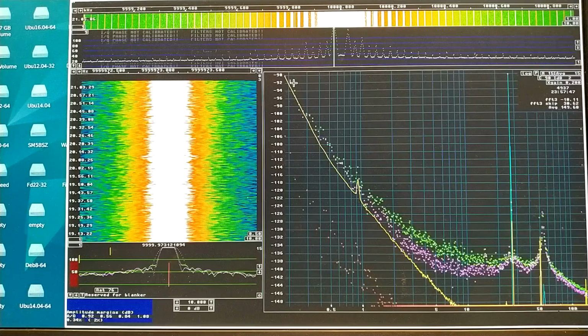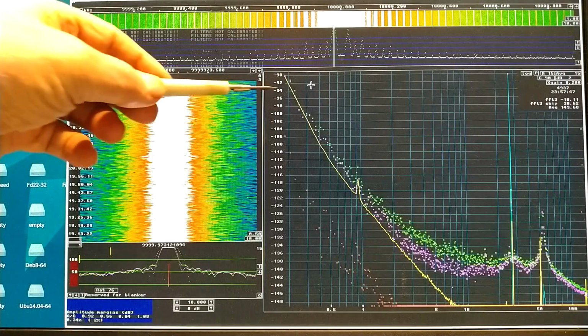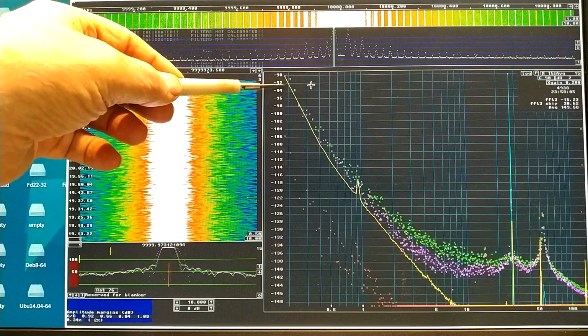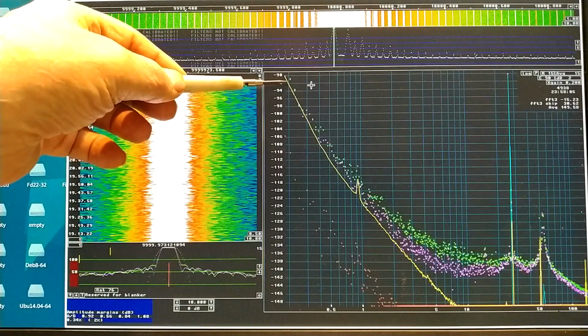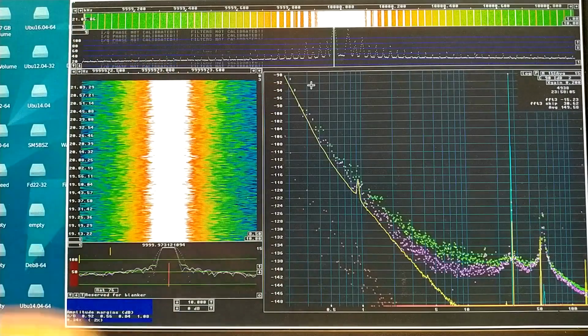The power level is now 14.9 dBm, 2 dB below the original setting. And this is not quite as good. I see now minus 92 dBc per hertz at 0.2 hertz. I will make a linear scale and read out some points.